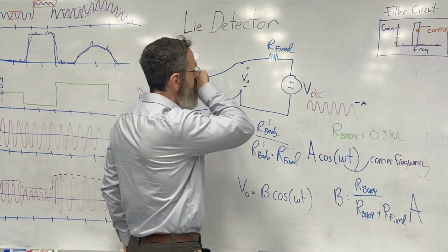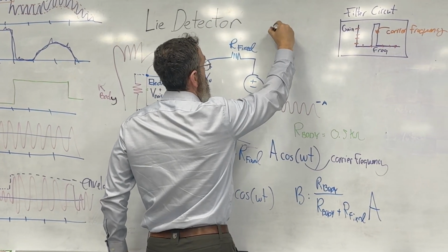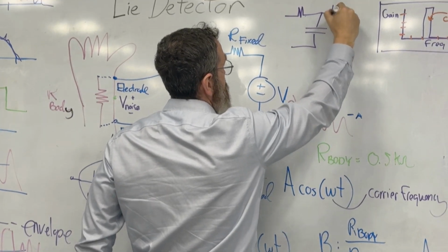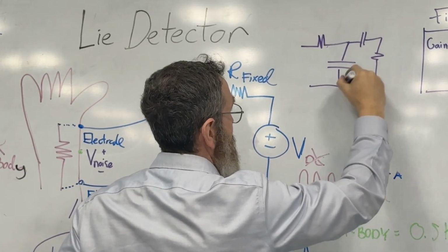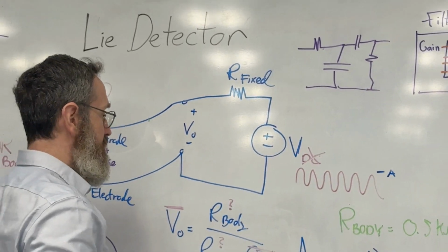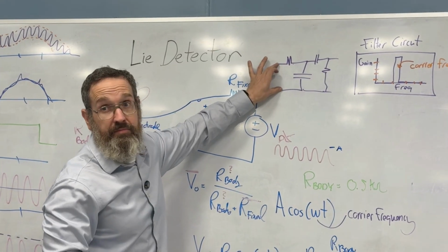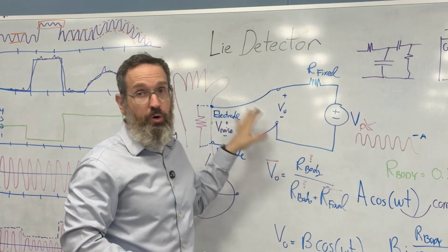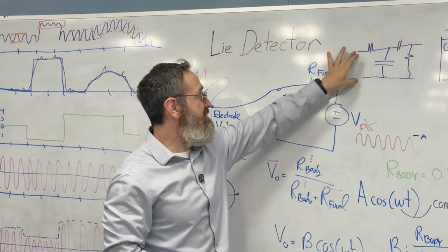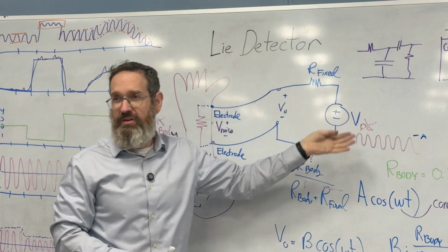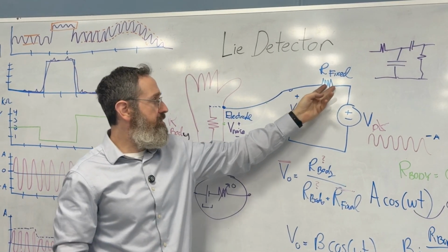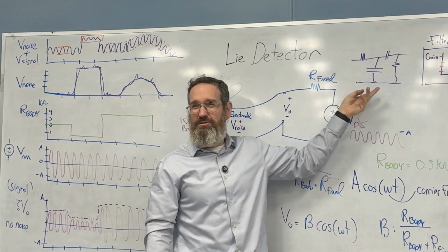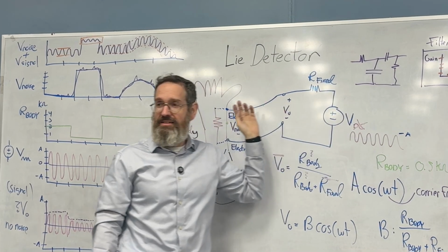I wouldn't try doing something like this, or however you would try to build a passive bandpass or something. Because if I connect this to these points here, I've now messed up the whole circuit. If I connect this to this, I don't have a voltage divider anymore, do I? I have a voltage divider where in the middle, I have 2 resistors and 2 capacitors. You can't just connect it like that, right?